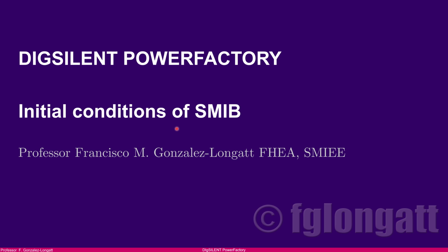Don't be confused. Initial conditions is very different to a classical load flow, okay? And that is especially true if you are working with DIgSILENT Power Factory, okay? There is a module inside Power Factory for calculating the load flow. That is the steady state condition, okay? And then when you are working with the time domain simulation, there is a specific calculation function that is dedicated for calculating the initial conditions, okay?